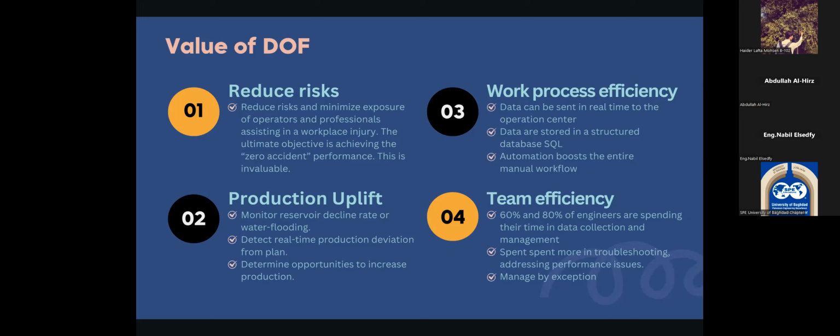If you're running a well test each month or each quarter, or even each half a year, then you need to collect all that data. You need to collect the salinity measurement or the water cut measurement for your well. You need to collect the behavior of the wellhead pressure from the sensors. So all that together needs a lot of time to collect. And then at the end, you need to analyze that data to make a decision about the efficiency of your well. In this case, if you're utilizing digital oil field, all that 60 or 80% is eliminated.